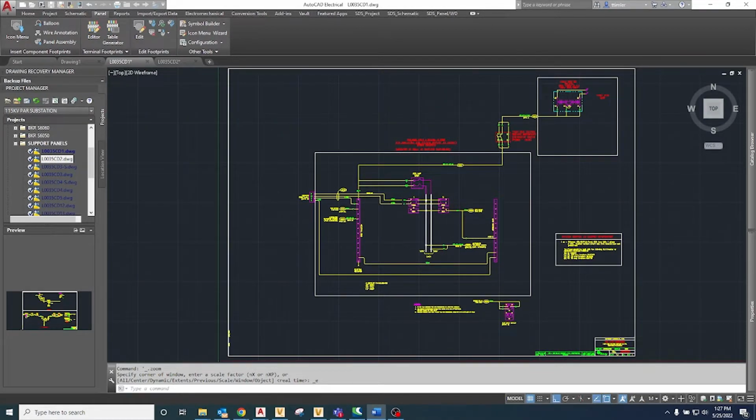This is a simple client template drawing of a station service AC panel. Instead of creating multiple instances of a typical circuit breaker like you see here, you may decide to use tie links on one-off template drawings like this to reduce unnecessary bloat in your symbol library.